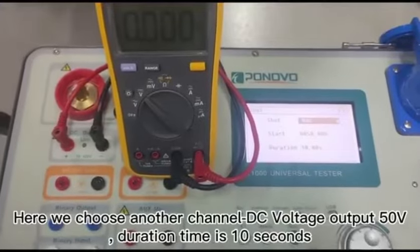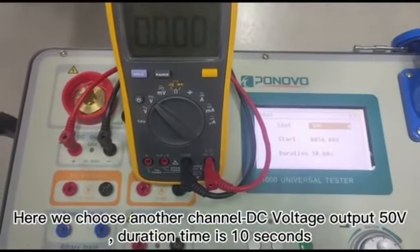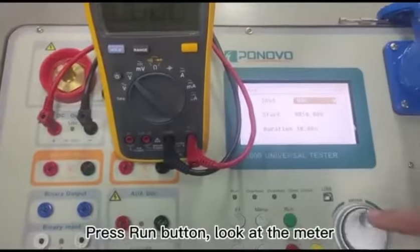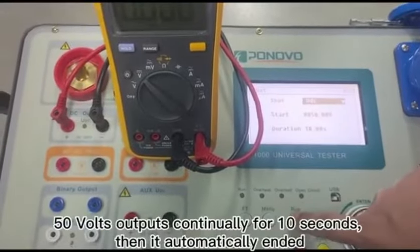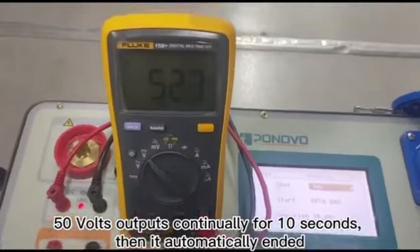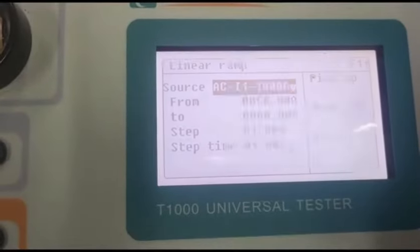Here we choose another channel, DC voltage output 50 volts, duration time is 10 seconds. Press run button, look at the meter, 50 volts outputs continually for 10 seconds, then it automatically ended. Third test item, linear ramp.